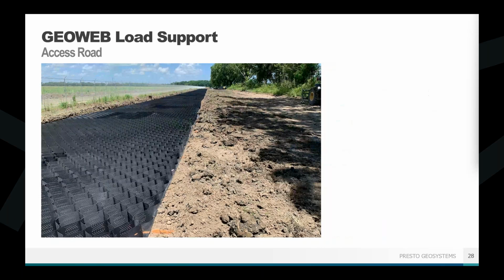So the 1,000-foot section of installed GeoGrid was removed, and it was replaced with a layer of 4,800 pound per foot enhanced woven geotextile, which is a relatively strong woven geotextile, and then the medium size GeoWeb panels 6 inches deep. The original GeoGrid design had included 2 layers of GeoGrid and a total of 16 inches of high quality crushed aggregate. However, we successfully constructed using a lower quality aggregate sand mix that had been on site. So that's where that low quality aggregate ability comes in.